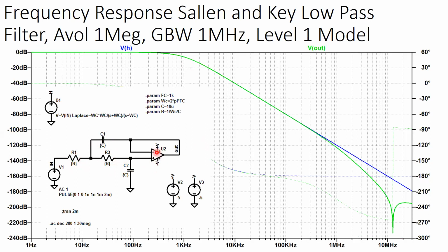And I'm using the proper op amp model from Linear. And then it finally hit me that while they're quoting a certain op amp gain bandwidth, when you read the data sheet and you see how much it varies, I said, oh my God, the gain bandwidth was limiting here. So it was working, but it wasn't working as a second order circuit.